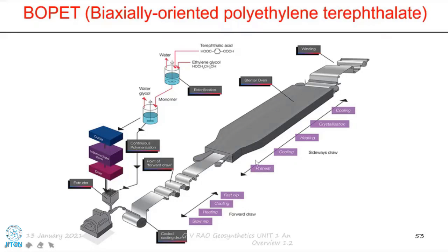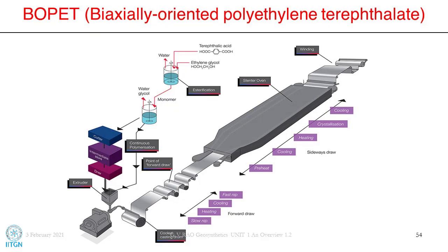And the point is that the way the system is being done, it is actually being widened. The video is trying to show you in the process all this stretching in the lateral direction, which they are making a patent issue, so they will not show that. So here we are stretching in the longitudinal direction. Here we are stretching in the, it is a biaxially oriented PET sheet. It is made of spun fibers, like spun staple fibers, or it is a sheet.